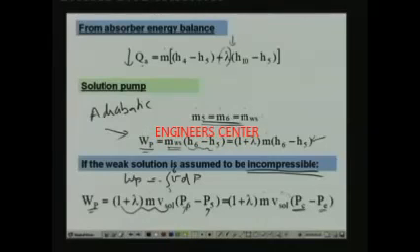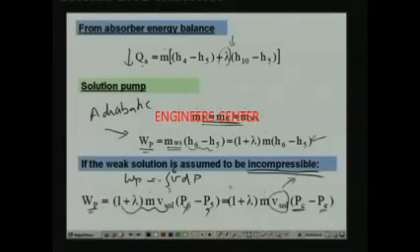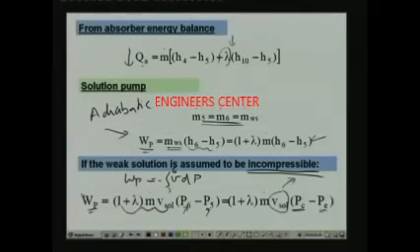Okay, and you can take an approximate value for the solution specific volume because it doesn't really vary much. So you can take some average value and you can calculate what is the power input to the solution pump. The power input to the solution pump, if you remember, is negligible compared to the heat input to the system. Okay, that means in COP calculation you can really neglect the solution pump work, but still you have to calculate